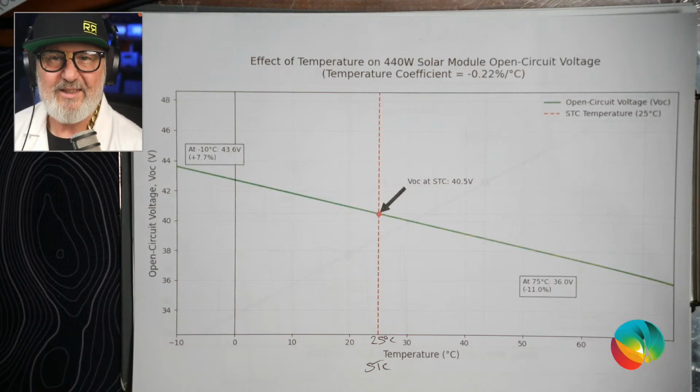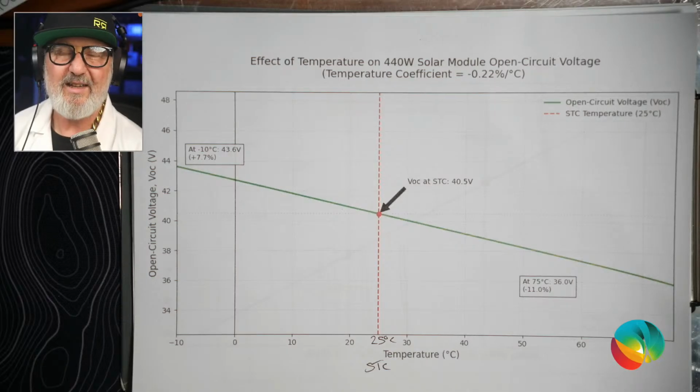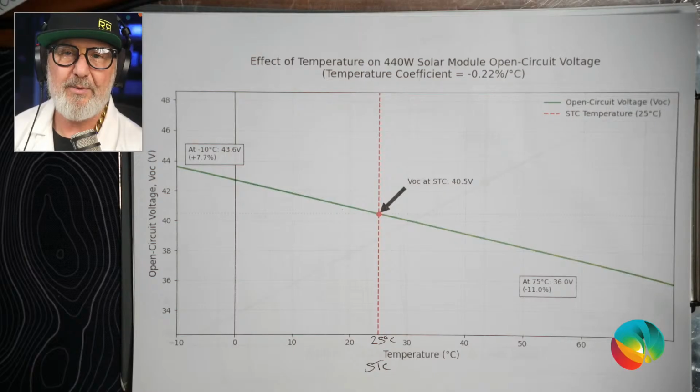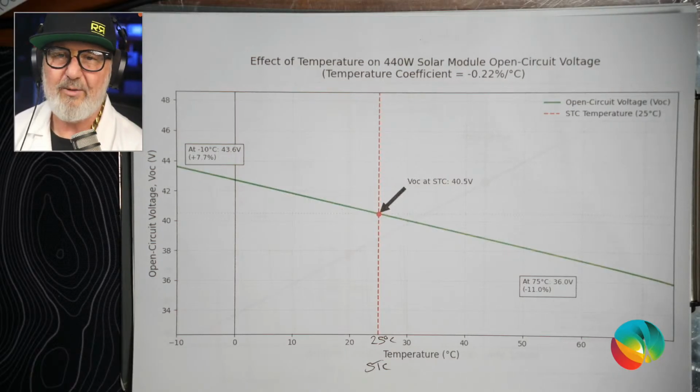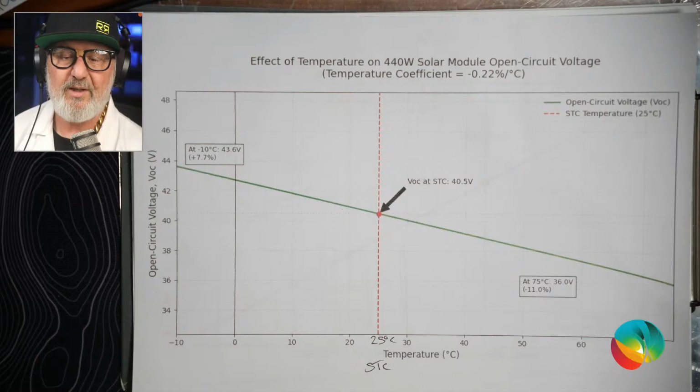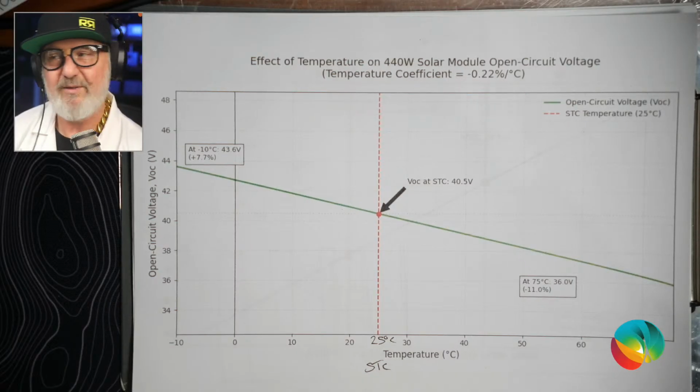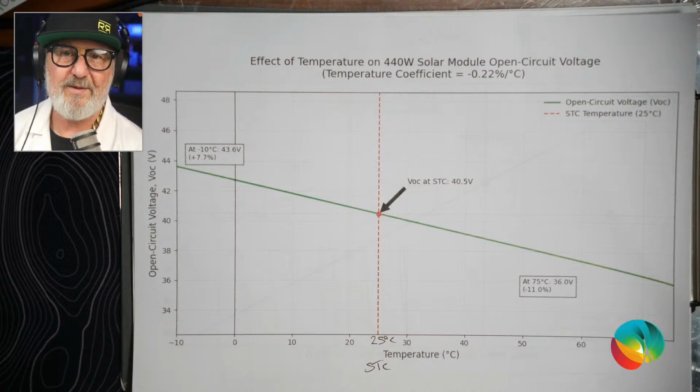But you have to actually look at the extremes, because it could be the one day that it gets to -3 or -5 is the day that you blow up your inverter. So my recommendation is, find from your meteorological service, NIWA in New Zealand, the BOM in Australia, or other services around the world, and also NASA have some global data too. What is the coldest ever temperature? And use that just to be sure. In fact, if you want to be sure because of climate change, put in a factor of maybe another 10% on that.